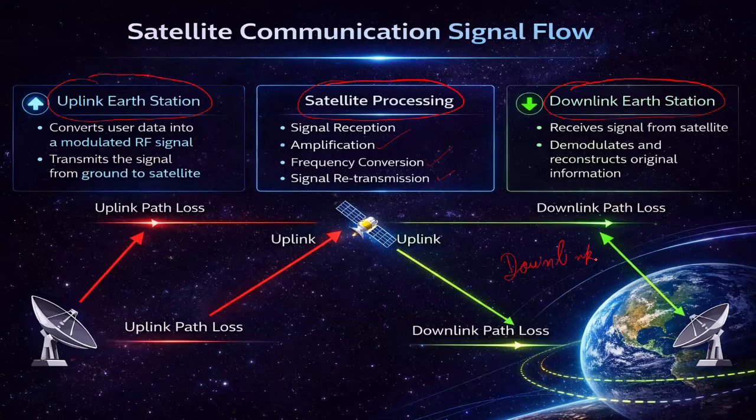One important concept you have to keep in mind is the signal loss. When you talk about NTN, signal loss is very important. You always think of it. As the signal travels through space and atmosphere, it experiences various losses. This includes path loss and environmental effects such as rain and snow. To compensate, the signal is amplified before transmission and after reception.